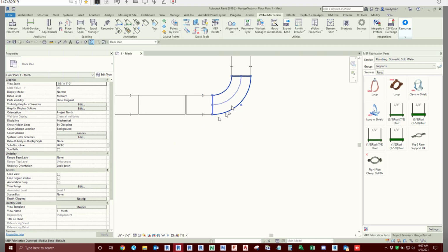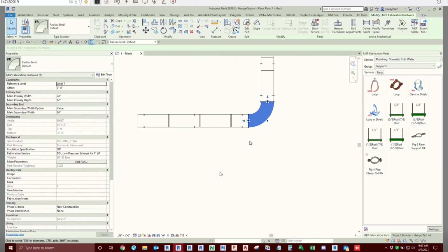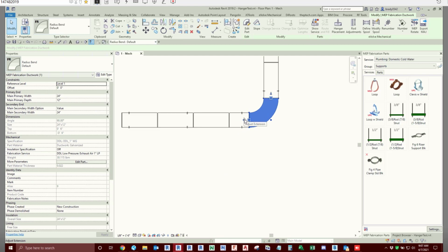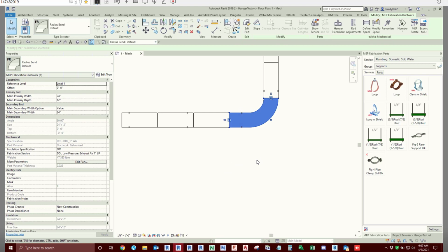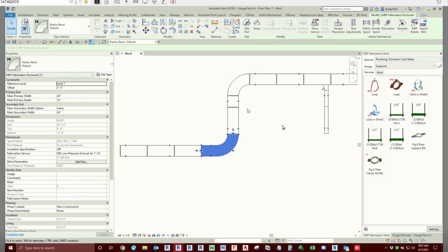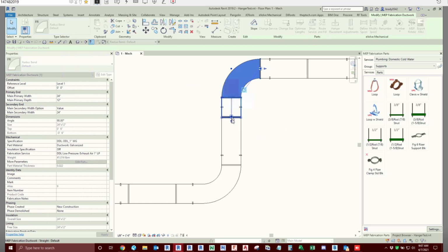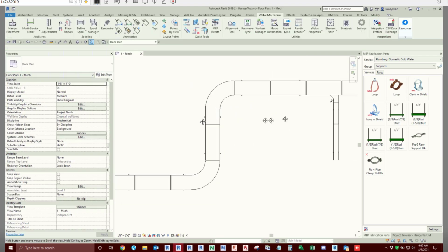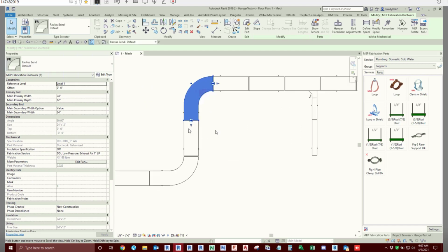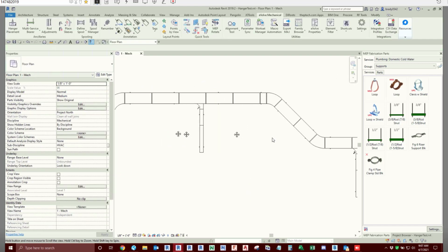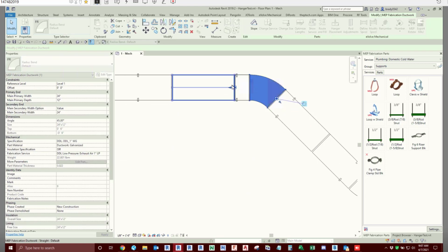But what I want to note to you is, if we're trying to cut out joints, we can go in here and it'll actually let you stretch this out. If we're actually going to burn fittings, this is a little bit tougher if you're not burning fittings, because then you have to note the throat lengths and all this other stuff. But it will remember the hanger on the end of this, and in my understanding, it stays connected to the run. So we can start stretching these out.